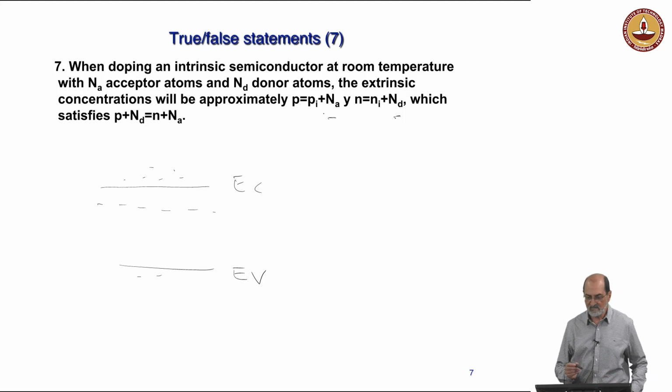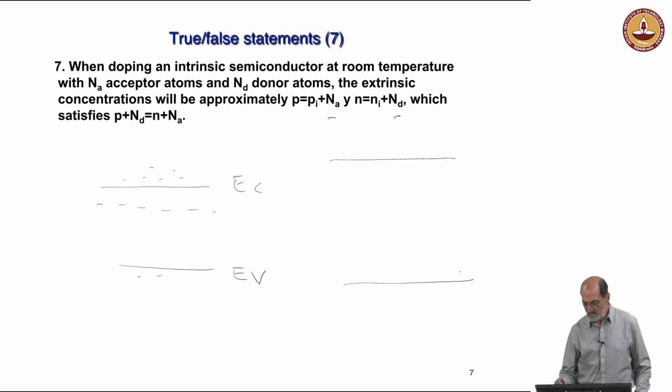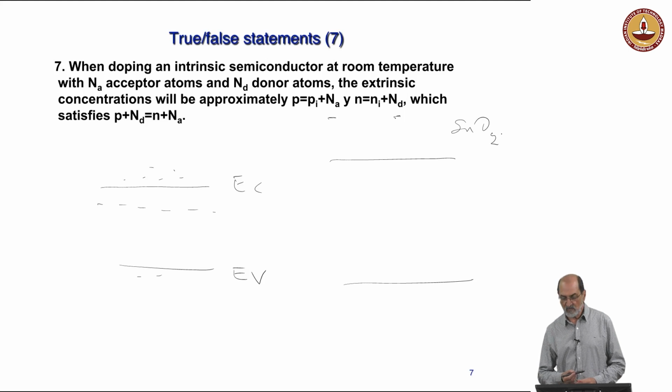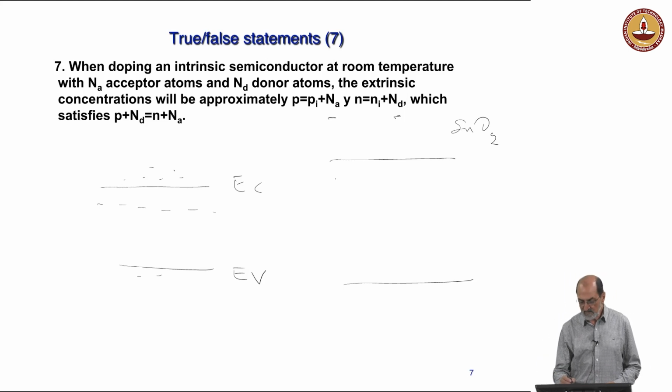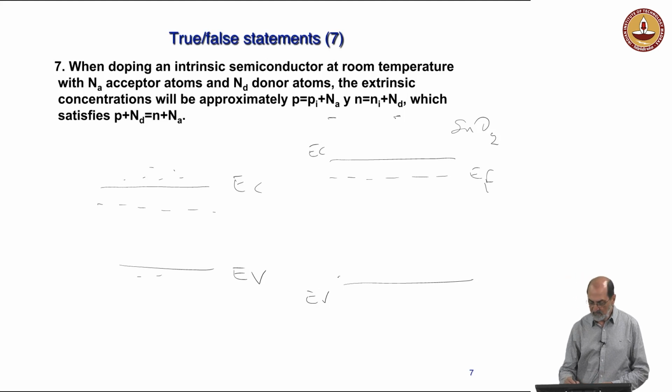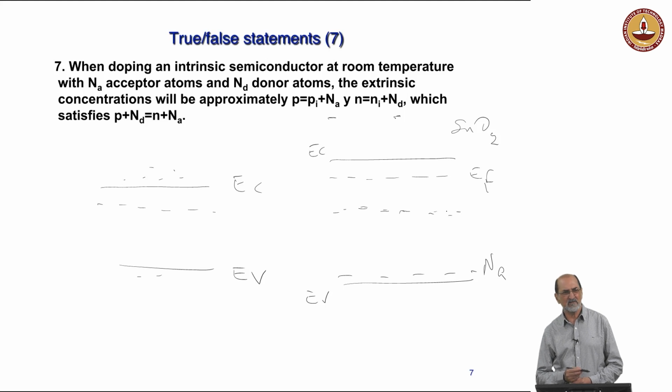And this is something I did not mention. I know that very well for tin oxide because it's the oxide I have worked the most. But usually things are like this. The Fermi level in an n-type is close to the conduction band. This is the conduction band and the valence band. Well, you say, I want this to be p-type. What do I have to do? Well, we have to add some acceptor impurities here, and then the Fermi level is going to drop. In principle, this should work, but it doesn't work.